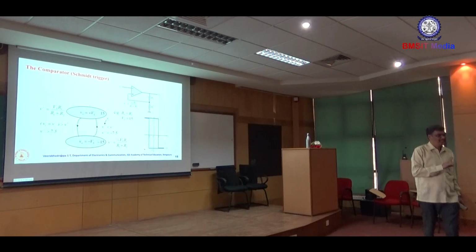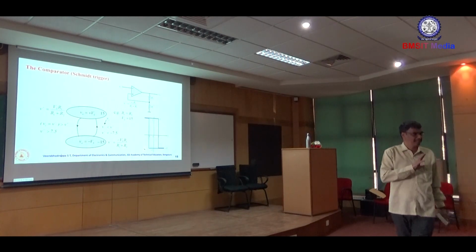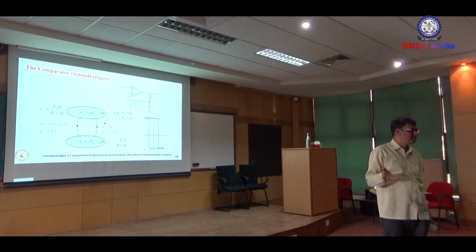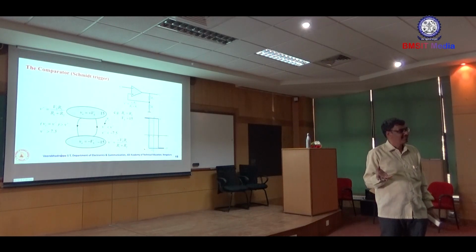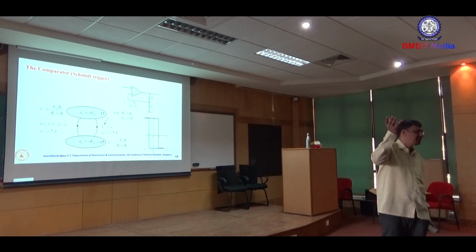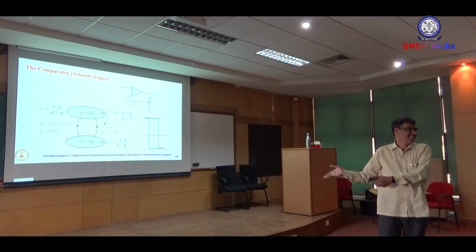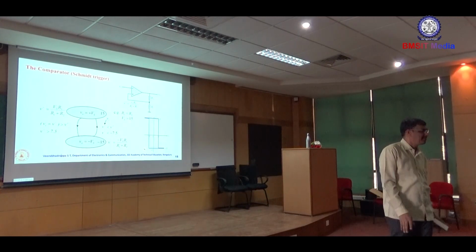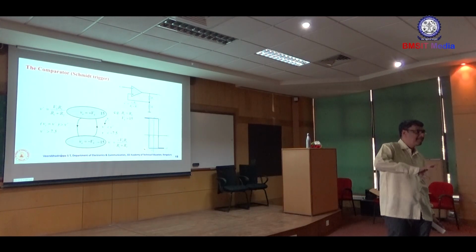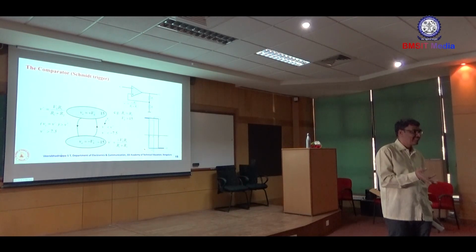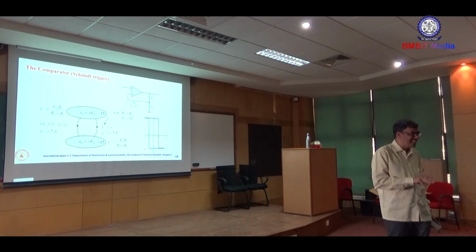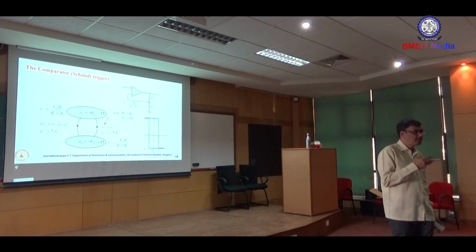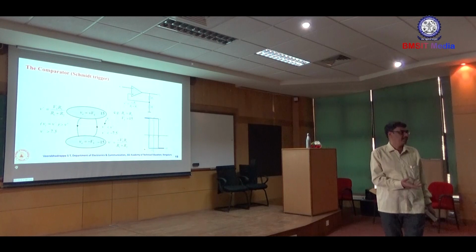You should remember this. Don't say that practically you got that in an interview. Sometimes they ask this kind of question. Is it identical? Then you recall your laboratory: no, sir, I got positive V saturation 11 volts and negative V saturation 10.5 volts. There may be many reasons. One is the components. Second is the measuring instruments not being calibrated. But you should tell confidently that they are equal.